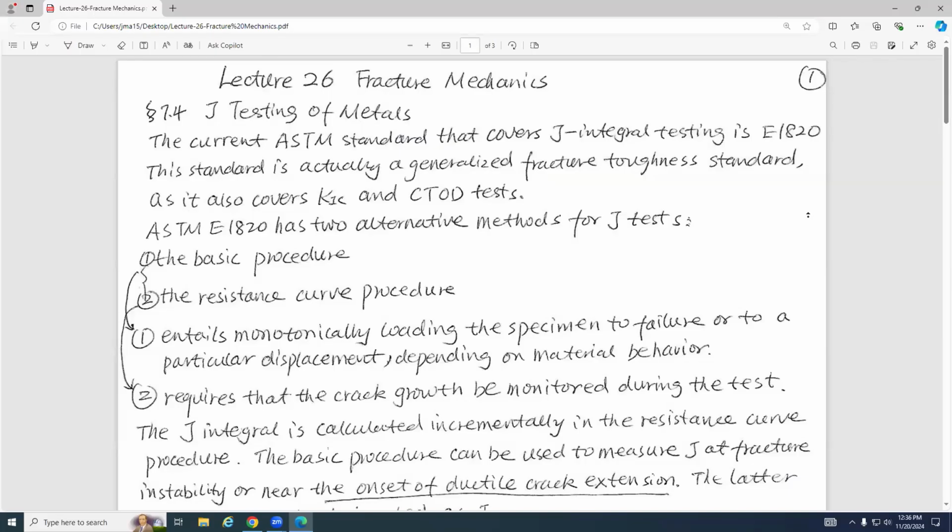And suppose I have a new material, very new, I just created yesterday. I want you to tell me the procedure to get the GIC. Then you tell me what ASTM protocol you are going to use, why, and then tell me the procedure, the steps. And then tell me how you can tell people that your final result is reliable. Through these hypothetical experiments, I can test your understanding of this procedure.